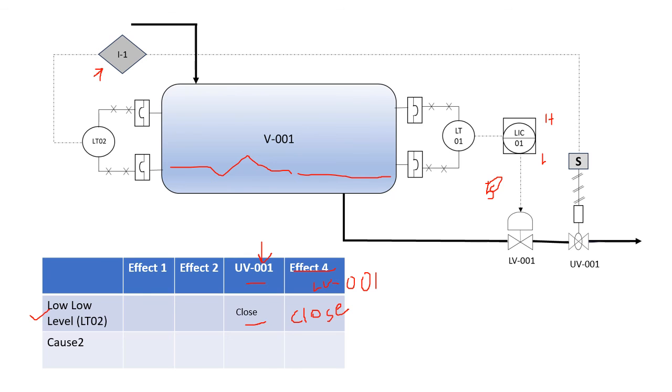So sometimes it is present, but otherwise, if you look through this diagram, in the P&ID there will be these diamonds, right? So by looking at the diamond, you can have some rough idea about what is happening in this particular case, what is the protection. But sometimes it may not provide you enough clarity. So that's why cause and effect is there to provide you much more clarity.